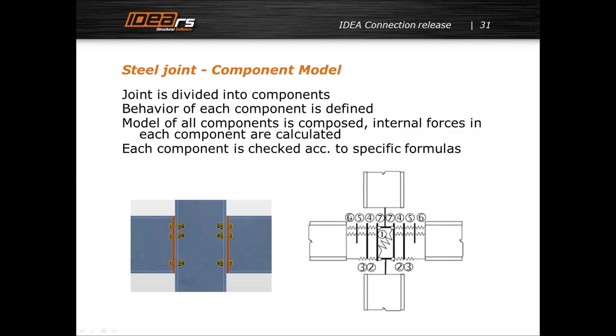And when you calculate this model, you get the forces in all these parts, like in bolts, in end plates, in flanges, etc. And for each of these forces, you can make the check according to Eurocode. Each component is checked according to special formulas, which are described in books and in Eurocode.